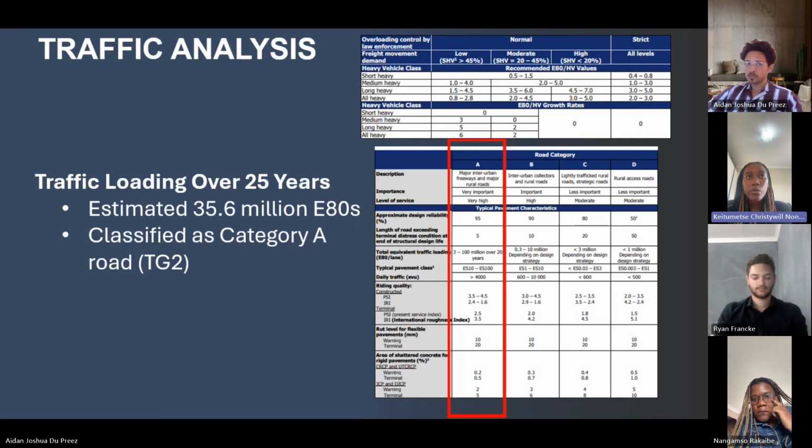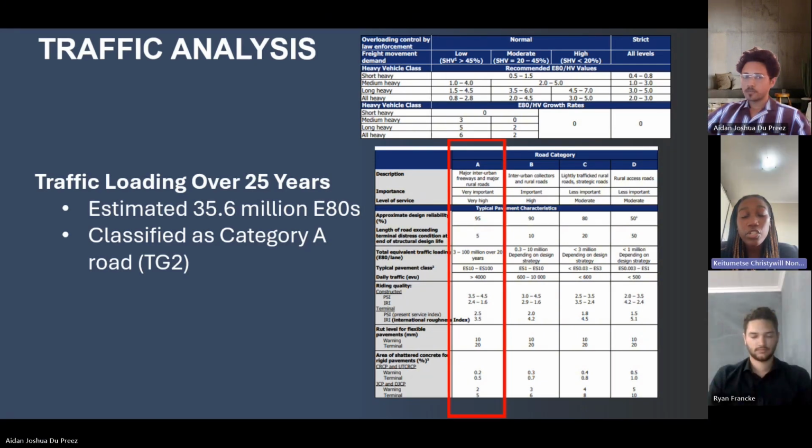For the layer design requirements, the base and subbase layers must be designed to handle cumulative load efficiency, and the surfacing layer should resist fatigue, rutting, and cracking, resulting in a material selection of high quality materials with the appropriate stiffness for load bearing capacity, which are essential to durability. The results and recommendations for traffic analysis are as follows.